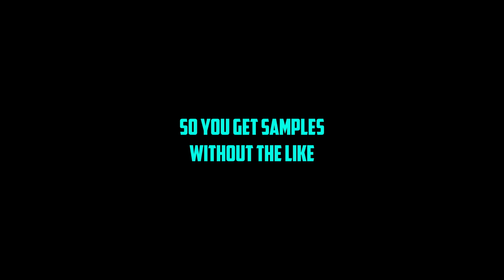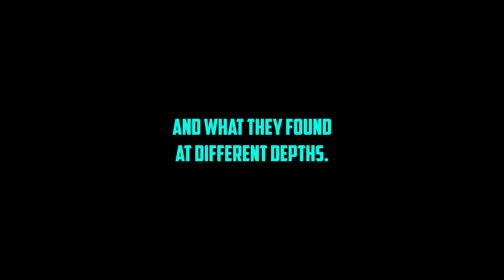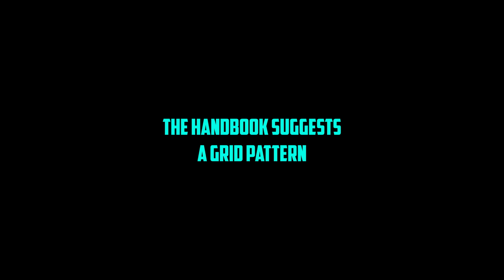It is. You use a jet of water or sometimes a bentonite slurry to break up the soil at the bottom of the borehole. The returning liquid carries the soil particles up. Ah, so you get samples without bashing them with a drill bit. Precisely. Less disturbance to the sample structure. Doesn't work so well in really coarse gravel or boulders, though. And all this borehole data gets logged really carefully. Absolutely. On standard forms, drawings, showing exactly where each hole was and what they found at different depths. The handbook suggests a grid pattern for the holes, maybe 15 to 20 meters apart, to get a decent picture of the whole site.